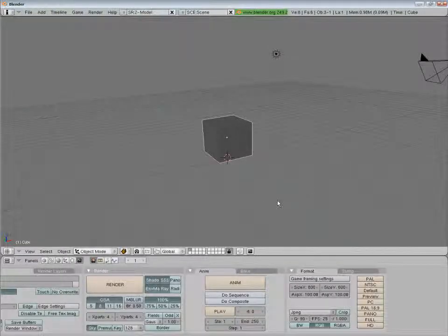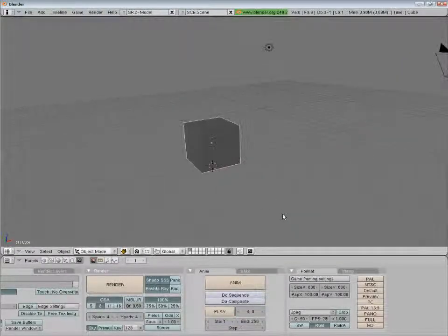Next in this tutorial I'll give you a quick introduction to animation commands. As we learn, this displays our current frame position. We can drag right or left to select any number, or we can hit the left or right arrow key on the keyboard to change the value by 1. If we press the up arrow key or down arrow key, we can increase or decrease the value by 10.